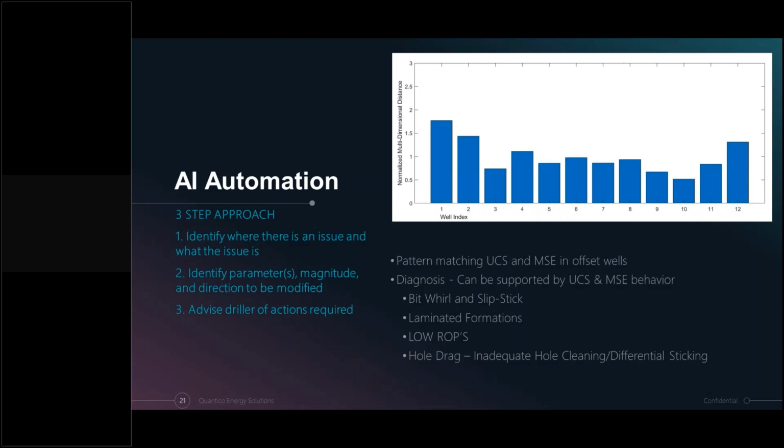Now, how do we actually implement the AI automation? I think it's pretty well known that there are companies and contractors out there too, but you can contact them and say, for each section, tell me what you or other operators see as a range of drilling parameters. Operators have their standard operating procedures of well-known set points for each section. The issue with that is none of those give you the local optima of what weight on bit, RPM, and flow settings should be as the rock changes.